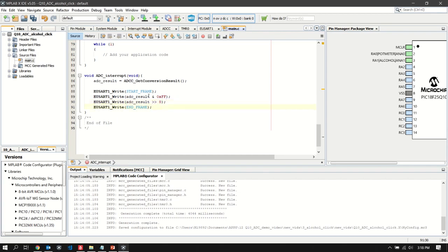So that's that. And then normally we'd also add this delay at the end here, but since we're kind of allergic to delays that actually keep the CPU busy for a while, we're going to just not have that. We had that before because we needed to have this function be kind of periodic at least, so it would run once every 10 milliseconds. Now we have the timer to do that, so now it's going to run once every 1 millisecond instead. And that is going to make the power debugger be able to receive the data without problem. So now we can go ahead and program the device.